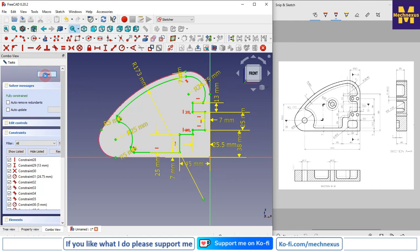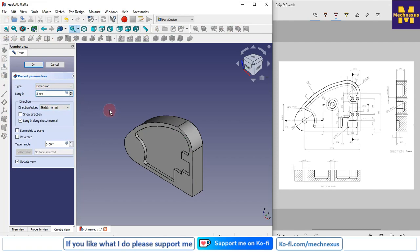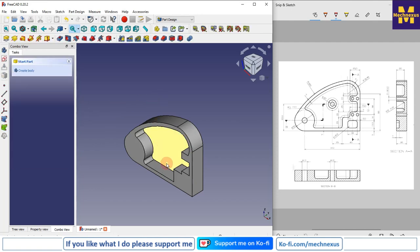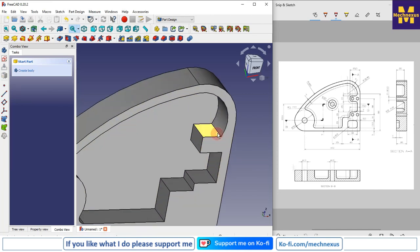Now I will close the sketch, and the cut depth is 20 mm. So we will go with extrude cut and give the 20 mm. Now we will select all the corners and provide the fillet.